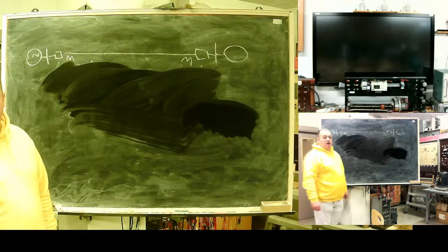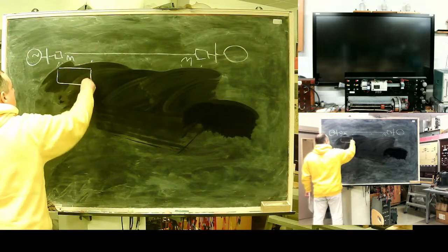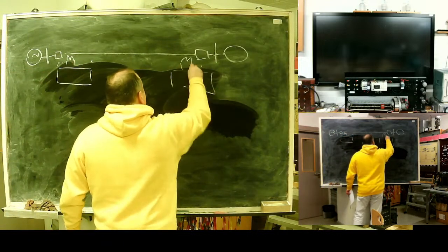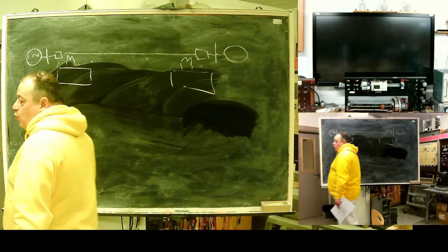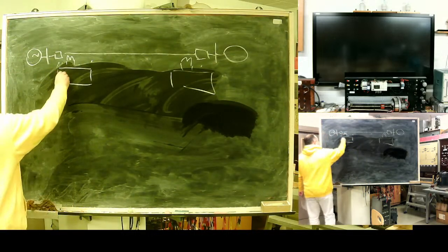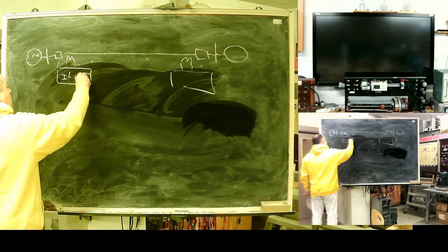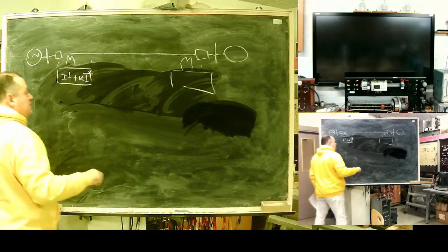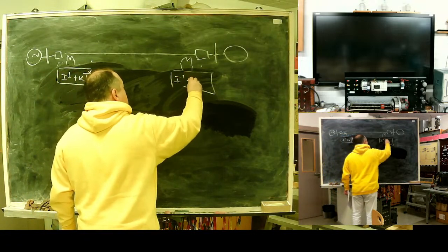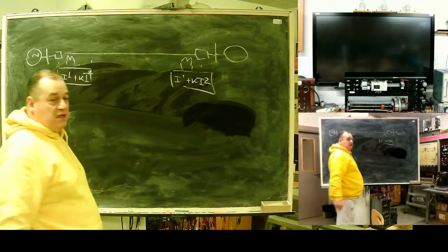The idea was not to compare currents themselves. Currents were subjected to a symmetrical component-based transformation. It was direct sequence current plus a factor of negative sequence current.